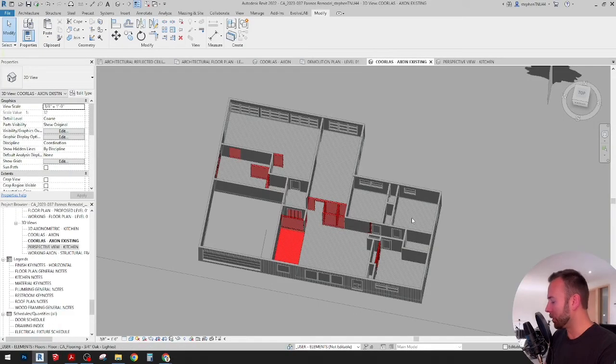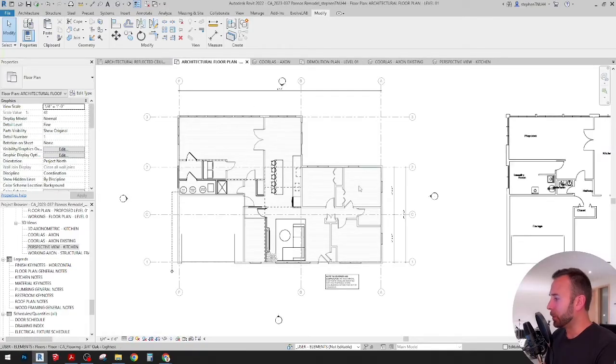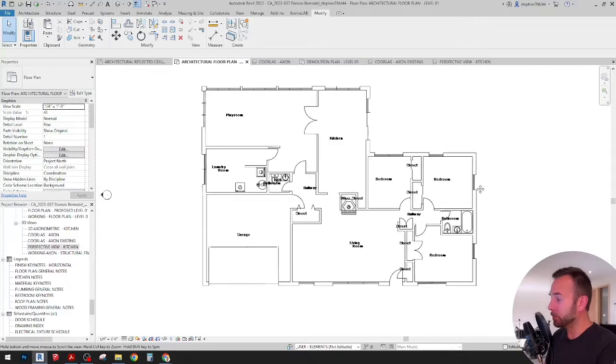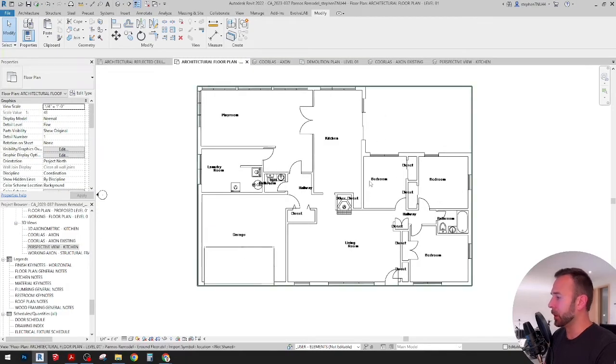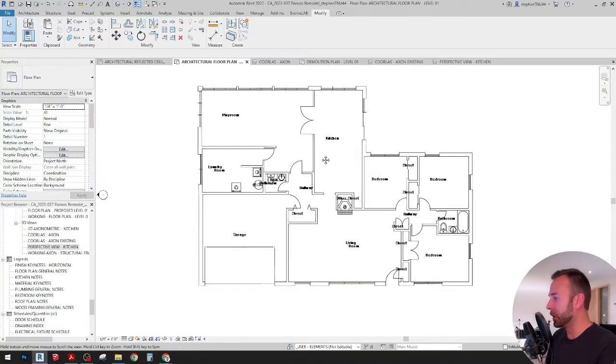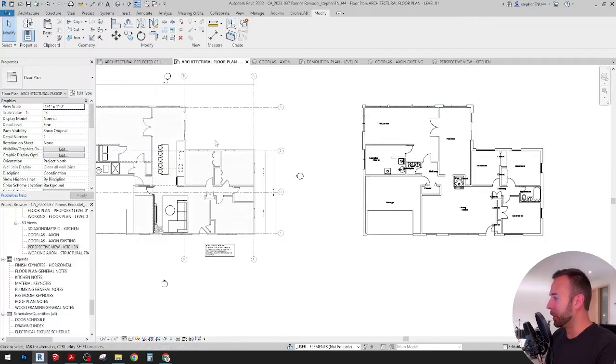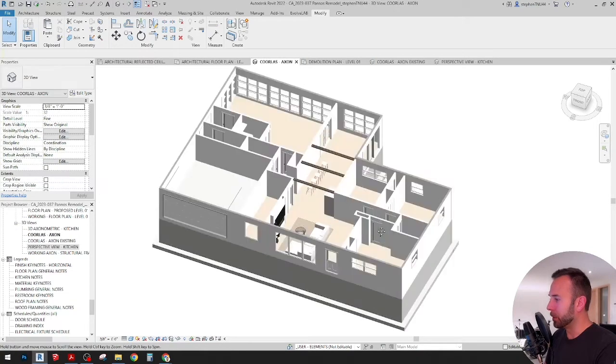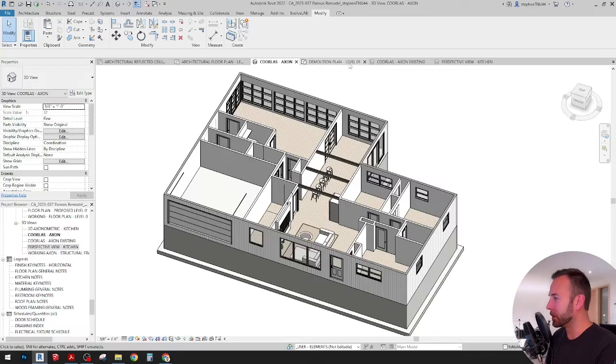So now that you're familiar with the software we used to document the existing floor plan, you can export a 2D CAD plan from Magic Plan, and this is what that looks like. We typically import it into Revit, start modeling our walls and windows according to the survey. And before you know it, you've got basically a model that looks like this.